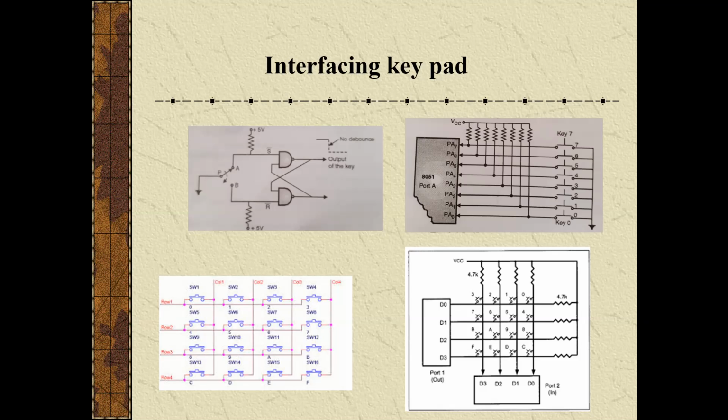In the case of a push button key, the metal contact bounces a few times, hence the voltage across the switch fluctuates and generates spikes in the signal. Therefore, it is necessary to debounce the mechanical switches. What is the debouncing of mechanical switches? There are two types, hardware debouncing and software debouncing.